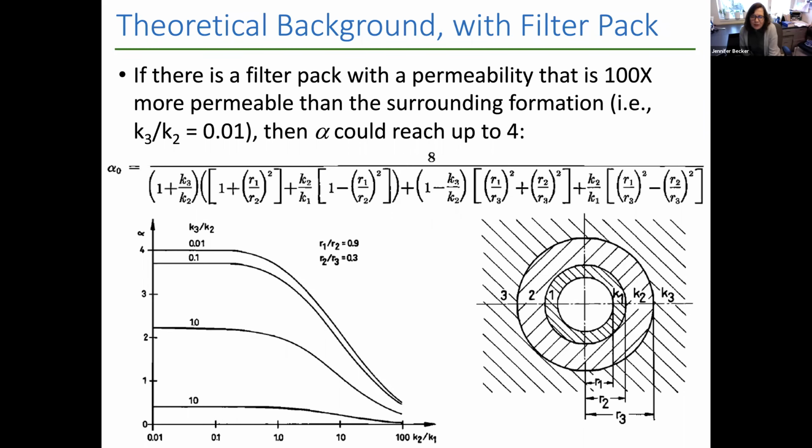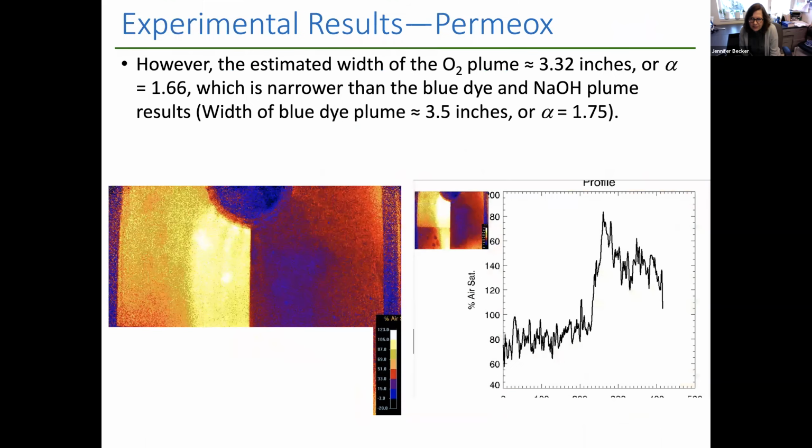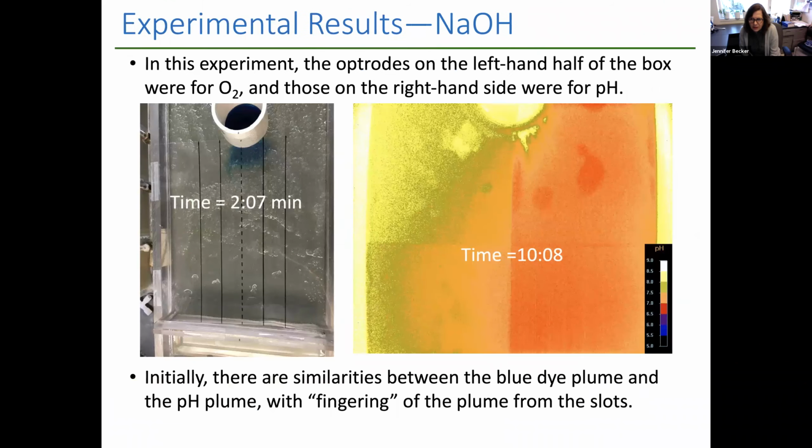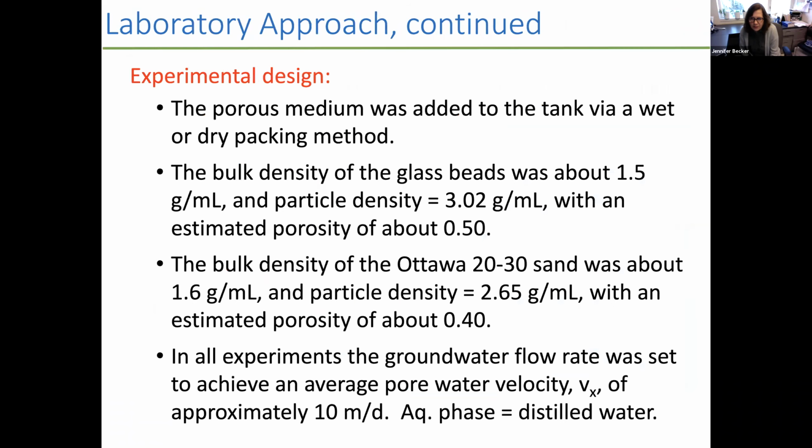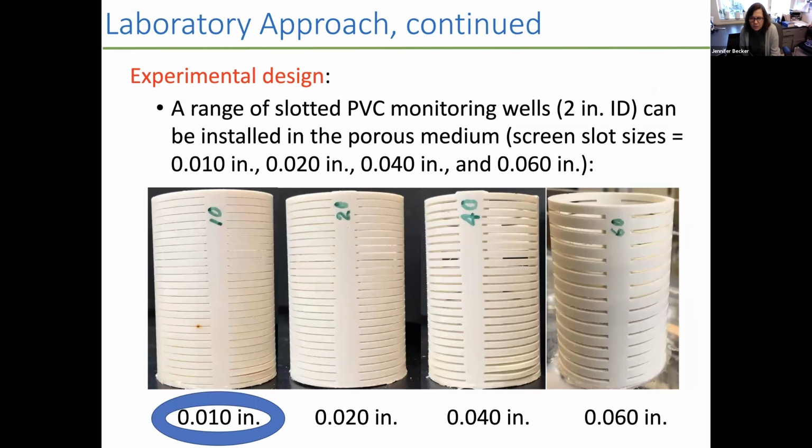But in general, you would think that if you have a very permeable aquifer, then you would, well, perhaps not. You wouldn't get good mixing, good dispersion. So I guess it's a bit of a trade-off, and I don't know how common that scenario is. If you had just an extremely permeable aquifer, it might be hard to select a well screen that was more permeable.